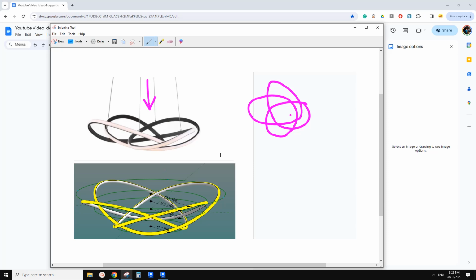Okay, and I'll just do a quick one here. So the top circle is the biggest one. Basically we need 4 points on this circle, and then in the middle there are 2, because we can't use 1 as it will create intersected splines, which we can't use for the sweep. We will need 2, and it will be here.